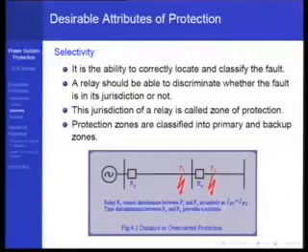This point has been confused a lot in the recent past, where quite a few blackouts have been pinpointed on maloperation of distance relays or overcurrent relays, and therefore there has been talk, for example, that zone 3 of the distance relay is no more required and so on, because it picks up on low voltage conditions, thereby creating some trippings which further worsen the voltage scenario and create a cascade effect.